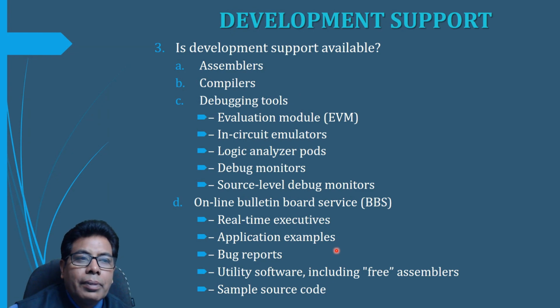Then next is development support. Is development support available? That is the question you must ask yourself. See the answer for this. Whether we have the assemblers, compilers, debugging tools, that is the evaluation module (EVM), then in-circuit emulators, logic analyzers, pods, debug monitors, source level debug monitors.